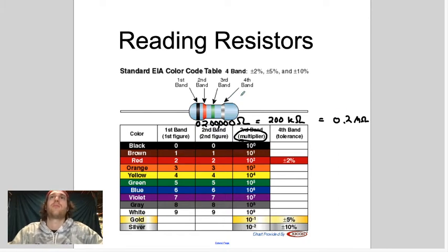So what's the last stripe? What's the fourth band on our resistor? Remember, that one's usually gold or silver. Just make sure you read your resistor kit, whichever ones you're using if you were to buy one. It'll tell you how to read it. This is what's called the tolerance. The tolerance is like how accurate our resistor is. We're humans making these things, and whenever you're engineering something, there's always the time you put into it and then the quality of the object.